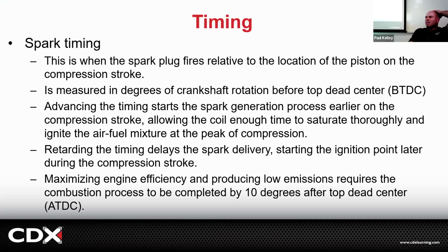It's like when the spark occurs relative to the location of the piston, though. So the timing chain is cam timing. Good observation. The timing chain controls when the valves open in relation to the piston. The ignition timing, or the spark timing, that's talking about when the spark occurs in relation to the piston, right? Valve timing is valves with timing chain or belt. Ignition timing is spark, which could have been due to distributor rotation, or the computer is going to control it on the new stuff, okay?